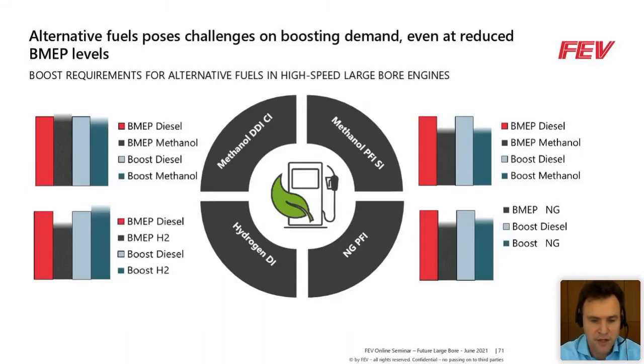And also, if you stay in boosting, what Arne also said very clearly is that, for example, in case of different combustion systems that are here in the middle, we will have different requirements in terms of boosting. If here in the picture you compare a standard diesel engine, single-stage turbocharged, and in red we compare the BMEP level as 100% and also the boosting as 100% of the requirement for diesel. Here we see that different combustion systems will require different boosting levels.